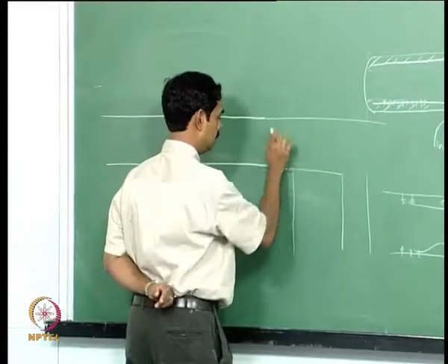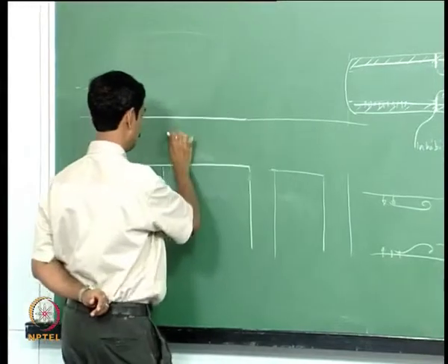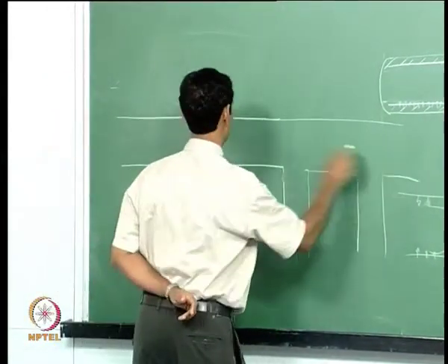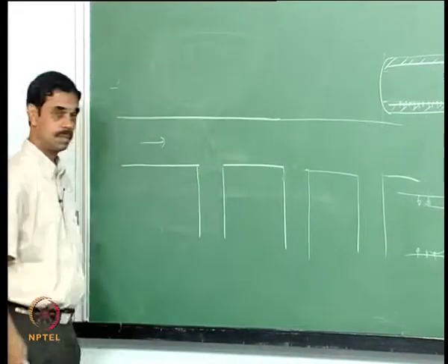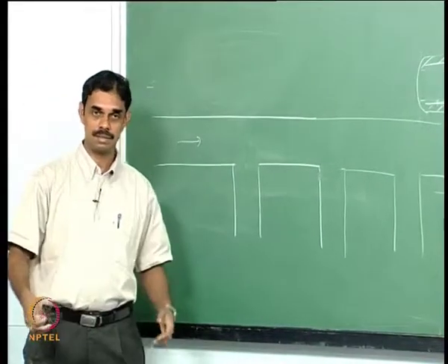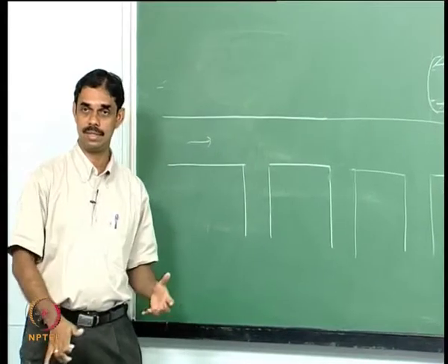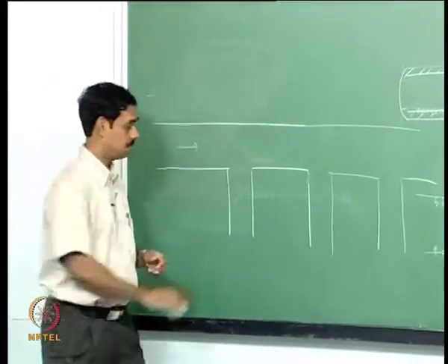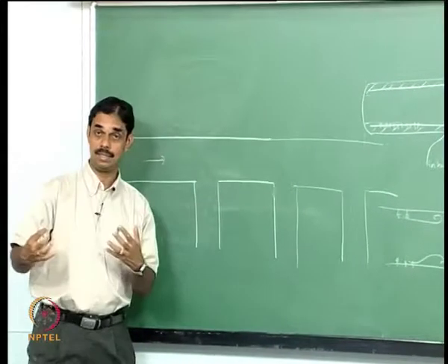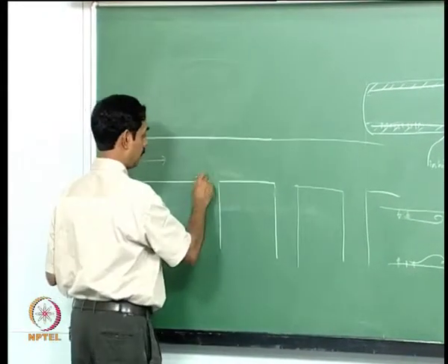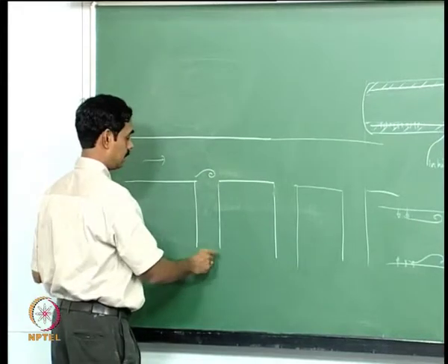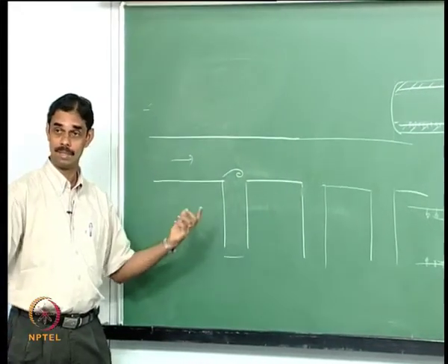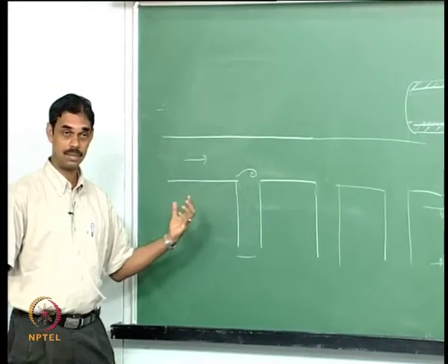you have branches and so on, and these lines are very, very long, and sometimes some branches may take more gas, some may not need gas, some may. So sometimes the moment you close some branches, many times instability develops, because you have vortex shedding and now you have a resonator here, and then you have very large amplitude sound, and it will be quite strong.